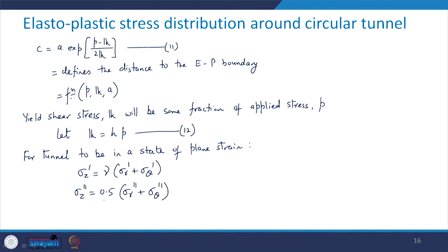Now, why this 0.5? That in the plastic state your material becomes incompressible, and you know that for an incompressible material nu can be taken as 0.5.